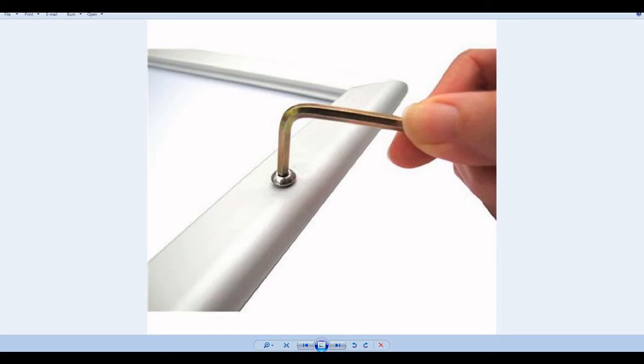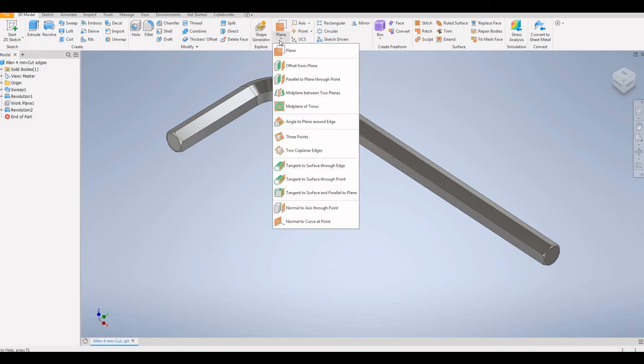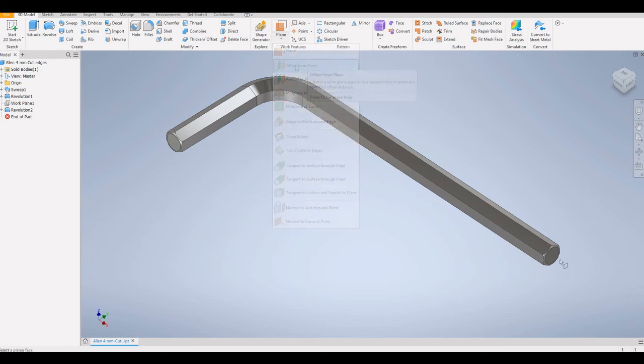For that reason, I edited my geometry file. It is a simple procedure to do. It depends on what software you use. All you have to do is just split these surfaces at both sides. Using Inventor, I would choose offset this plane as the reference. Cut these surfaces. I will show you in one slide how to do it at distance minus 10 millimeter.